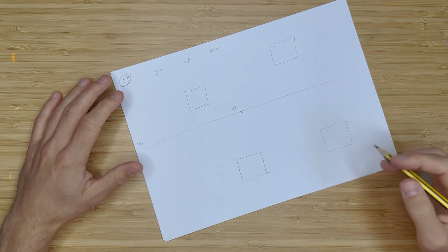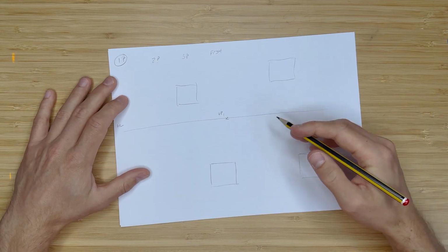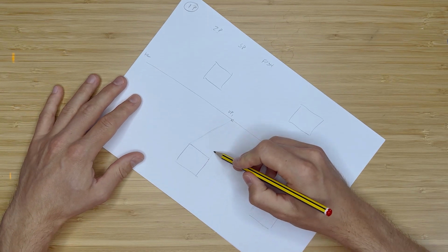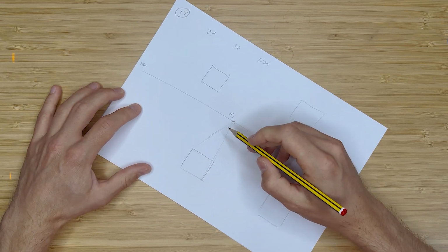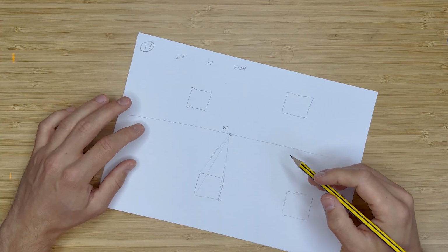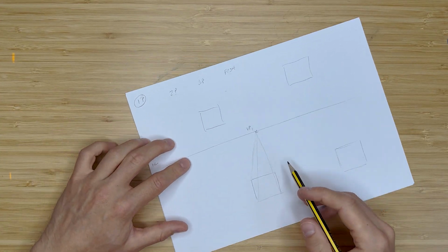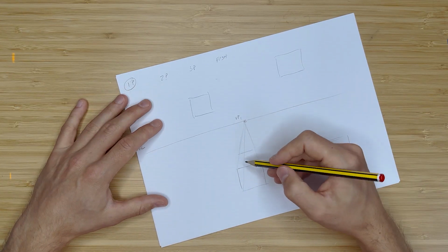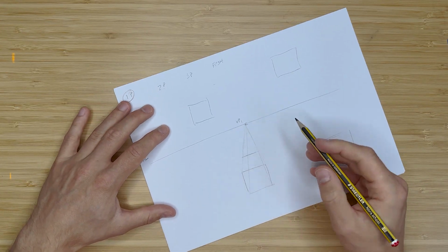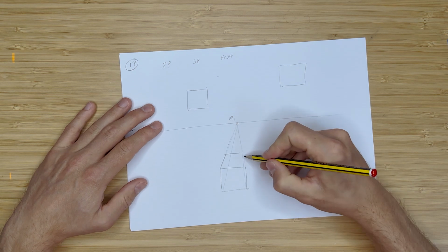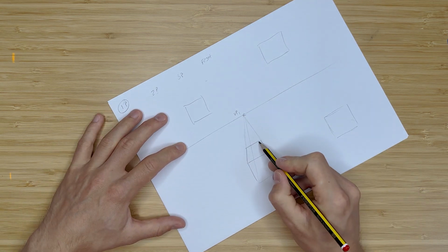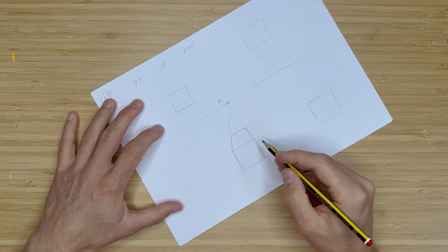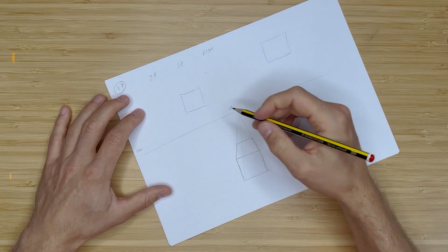And what's going to happen is this is going to vanish back to that point. So from this top point here, we're going to go back to our vanishing point. Same for the bottom point, back to the vanishing point. Exactly the same for these other ones, but let's finish this one off first. Say we want this to be a cube, we can go across there. You're not going to see the back part of the cube because it's hidden. So then we can make this line dark here, this line dark here, and there we have our 1 point perspective cube. Like so.